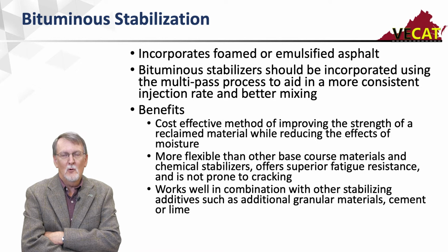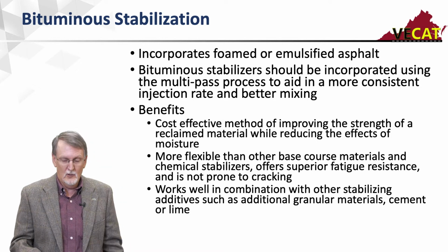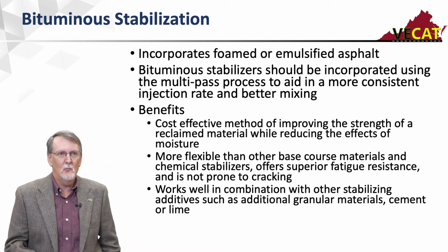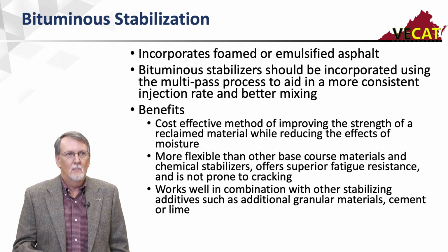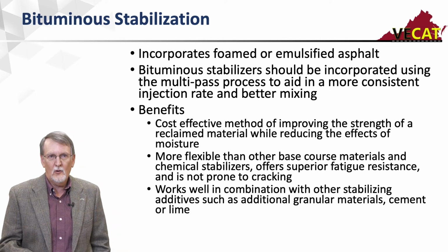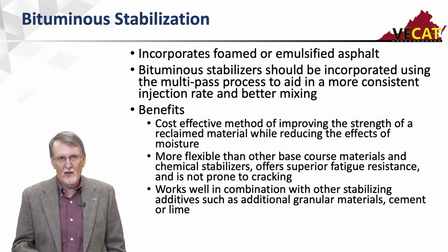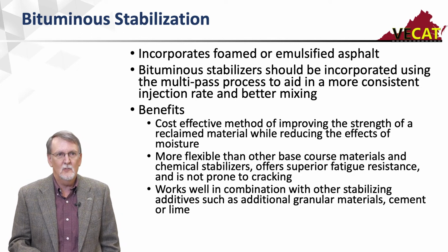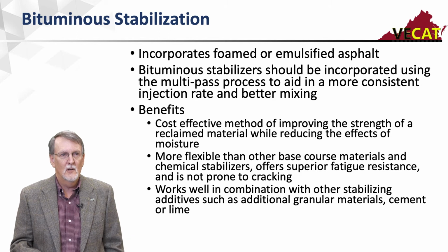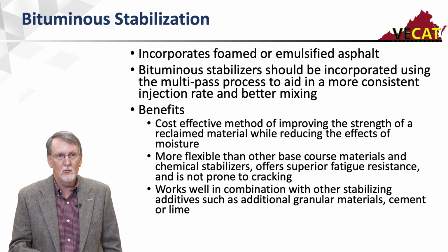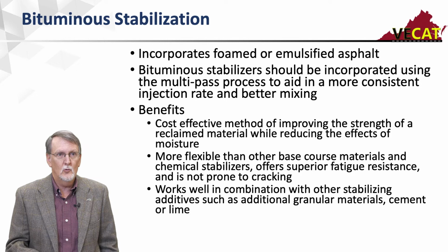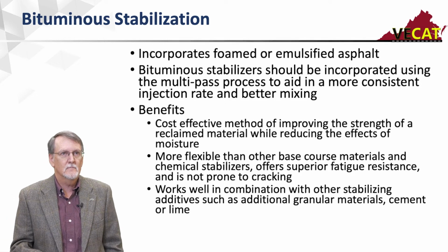If you start picking up more fines, you need to go to cement, and if you start getting clay, you probably want to go to lime. But the other nice thing about bituminous stuff, it works well in combination with other stabilizing additives. You can add other granular materials, or you can add a little cement or lime to give you a little better strength and a little better moisture resistance. So you will see those added occasionally.